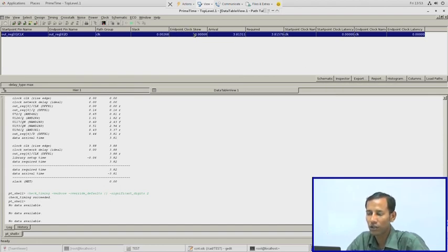that the skew is 0, as I have not set that thing. So slack is met, and this value of slack is very much nearer to 0. So this value, that means 3.88, means this is the maximum time, or the maximum operating frequency, 1000 divided by 3.88. This is the maximum operating frequency where this 16-bit counter can operate.